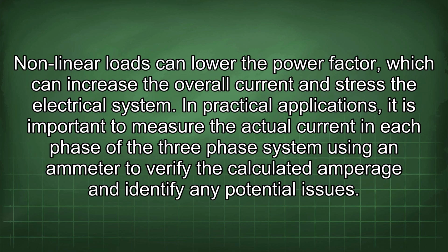Nonlinear loads can lower the power factor, which can increase the overall current and stress the electrical system. In practical applications, it is important to measure the actual current in each phase of the three-phase system using an ammeter to verify the calculated amperage and identify any potential issues.